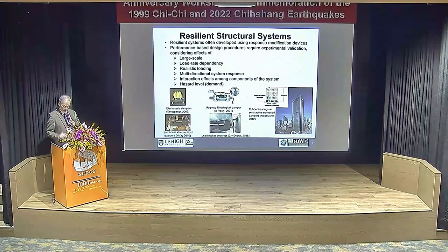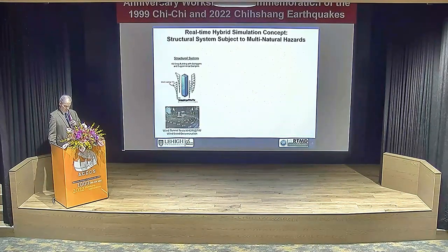And this is a little bit redundant, so seismic is the level of the demand. It's realistic loading. But we want to be able to assign the level of hazard, so we look at performance engineering versus the fragility of the resistance. So let's just briefly look at hybrid simulation just to describe it here. So if you have a tall building, 40 stories tall, we're interested in looking at the performance of this. Could be any event, it could be wind, earthquake. It'd be very difficult to put it in your lab because the lab's not going to be as tall as the building, especially scale does matter.